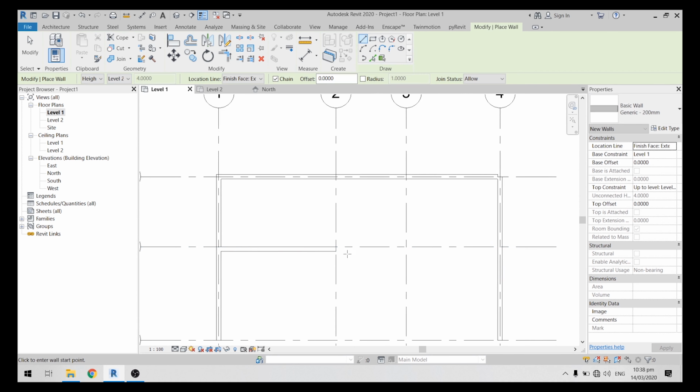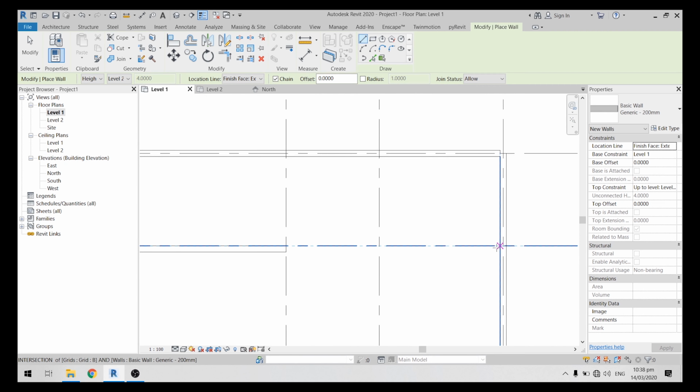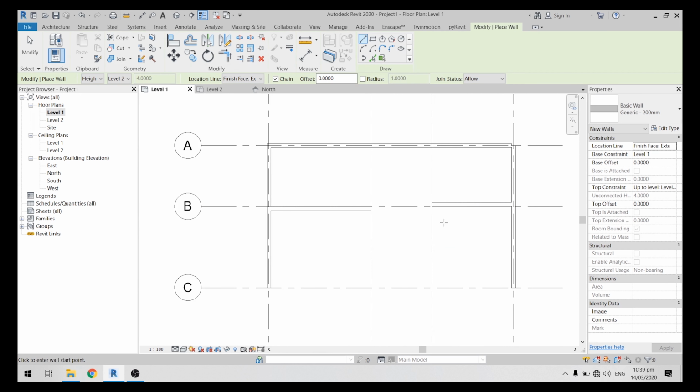But if we then click escape, then create another wall here, if we are going to choose from right to left, let's see. Okay, so Revit will consider that the exterior part is below or downward. Okay, like that. So it's opposite.